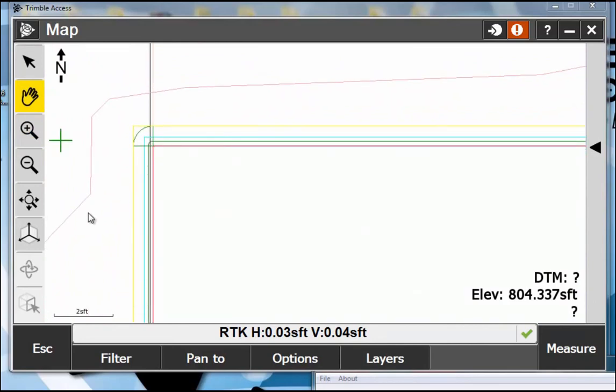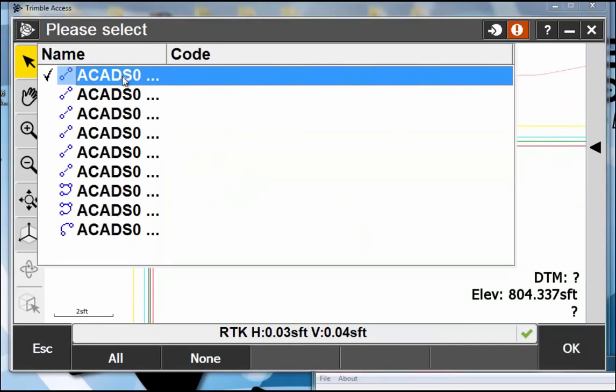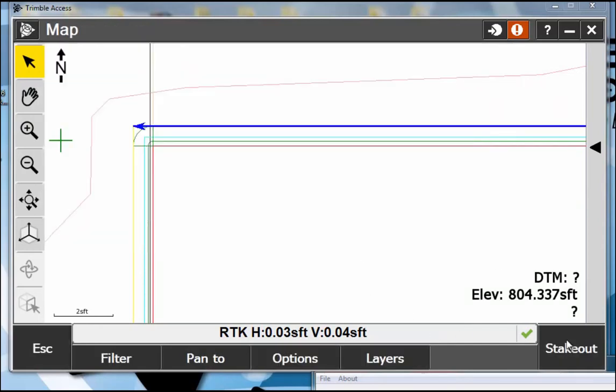All right, so here's my backup curb line. It might be kind of hard to see with the display here, but notice what happens. I think this is a layer I have to turn off. We'll see. Notice what happens though. The point I'm trying to make is, when we export a DXF and we have this line work, when I stake this backup curb in a DXF, the advantage is it's easy, right? It's an easy export. It's an easy thing to load. I don't have to open roads. I can do it in general survey.